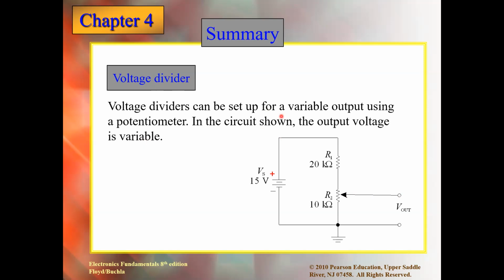If I ask you guys, can you tell me what is V out here? The formula for V out? V out is VR2, the voltage across R2. So we know the voltage divider formula.